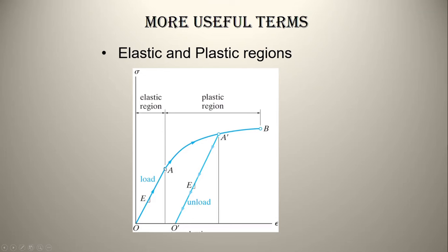But a strange phenomenon is noticed that if you go beyond the elastic region, for example, you keep loading the material, it follows this path. Now you start offloading. Well, the strain starts to reduce. As you're reducing stress, strain also keeps reducing. But a point comes where the reduction in strain is much less now. And you see that instead of following back when you're reducing the load, it doesn't follow the same graph, rather it follows this graph.